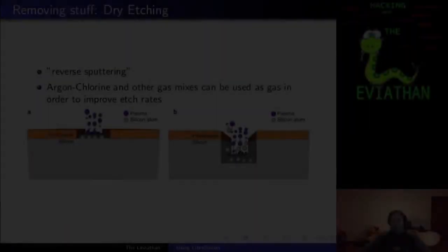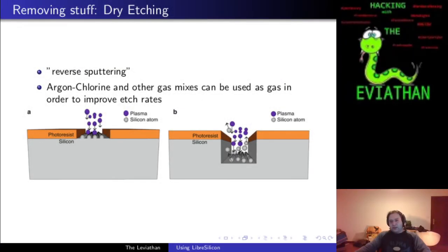Common sense. Dry etching, also known as plasma etching, can be described as sort of an inverse sputtering because it's a similar principle. In a low pressure atmosphere, an etching gas chemical mix is flushed into the low pressure chamber and then agitated by an RF setup which bombards the target and removes the atoms from the target atom by atom.